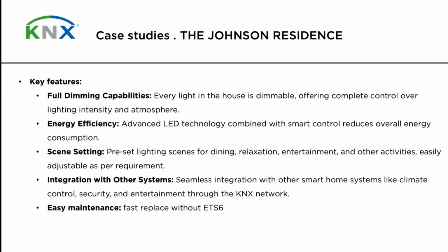That's perfect. In a university, in a hotel, convention center, do not link one button with a group of lights. Don't do that. Instead of that, work with scenarios. This is something that we learned in the KNX training. You need to work with scenarios, yes or yes. There is no other option. Do not make groups. Work with scenarios. So a scene all on.